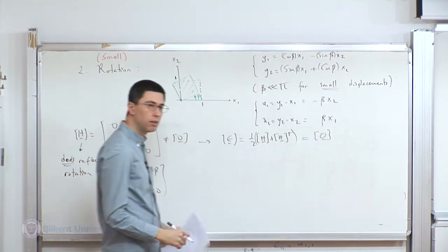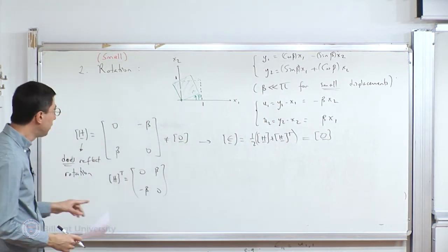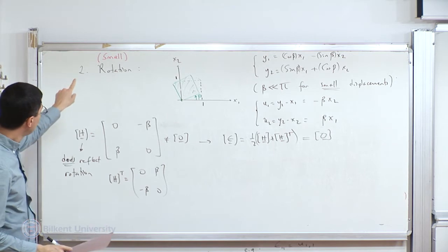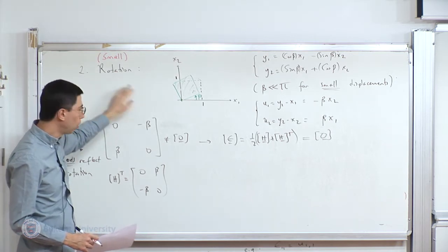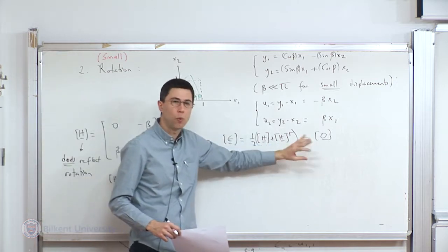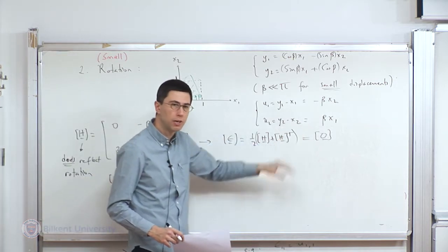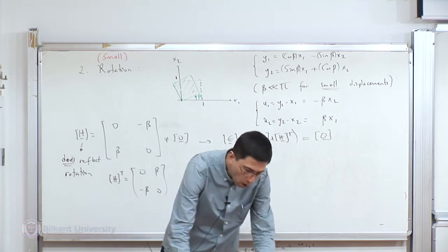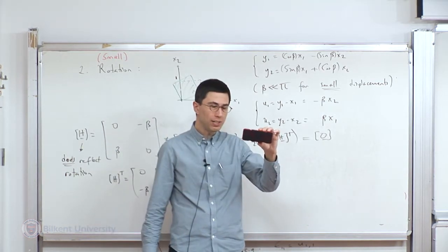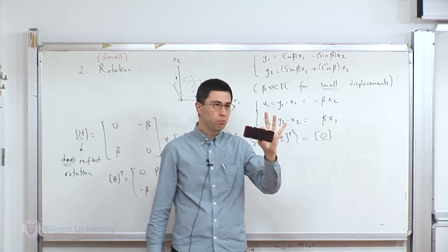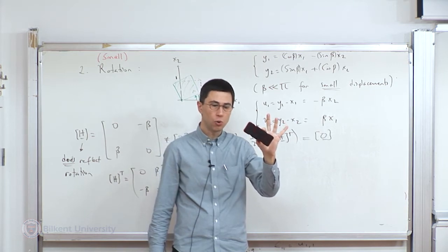Okay. Right, so the point here is that for small rotations, rigid body rotations, epsilon also does not display it. And indeed, that's something we want, because if I rotate something, I'm not putting any stress on it. It just changes its orientation.